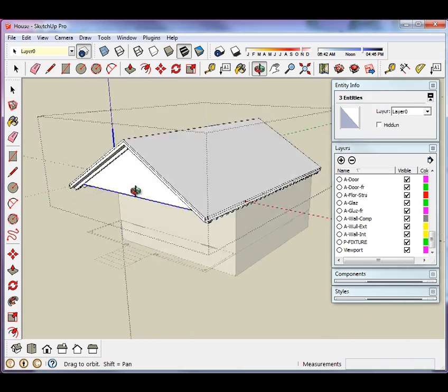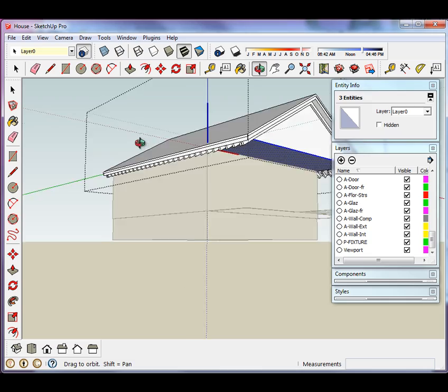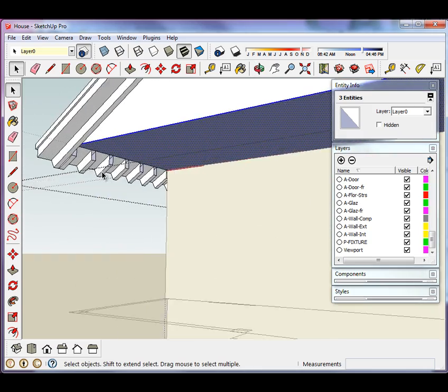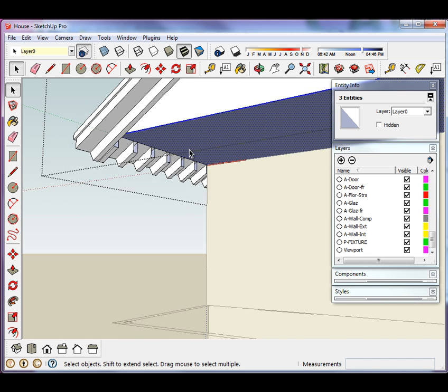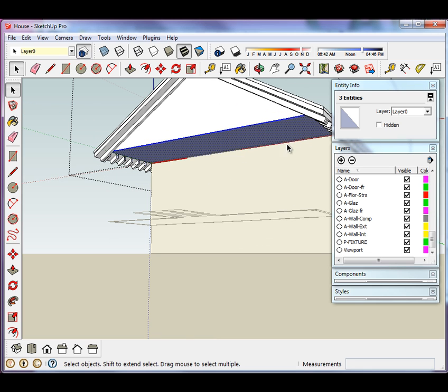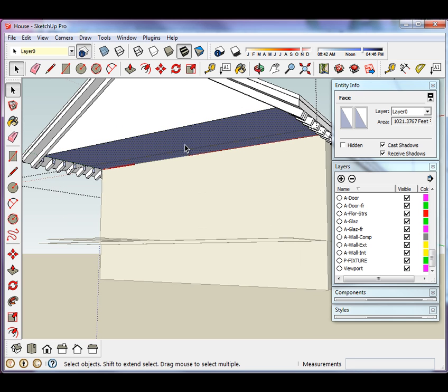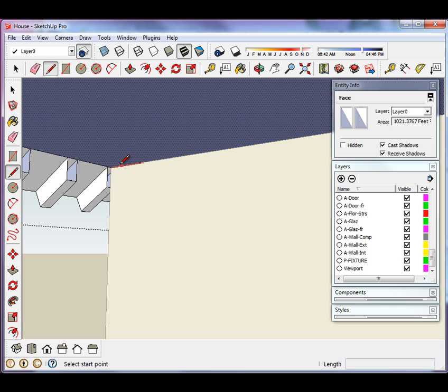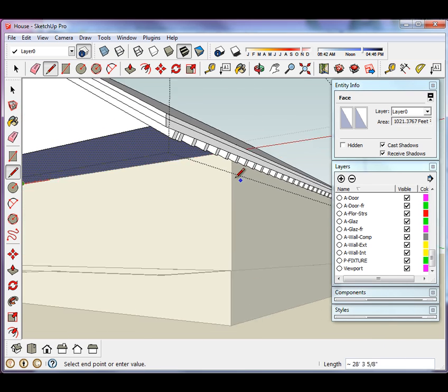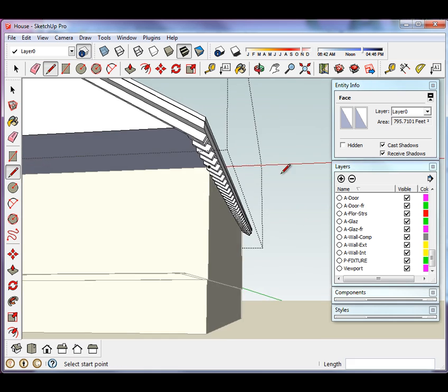Now, what you'll see is the basic roof structure here. We still need to edit somewhat, because you'll notice that in the front we've got some exposed rafters, but in actuality what we would have here is we would build out a soffit, because we would still have our joist coming across our roof there overhead over the porch. And so what we could do is, you'll notice that I still have highlighted the roof plate plane, and what I want to do is I want to make sure I can trace a line from this intersection all the way across the face of the building to the opposite side to create a seam in that plane.